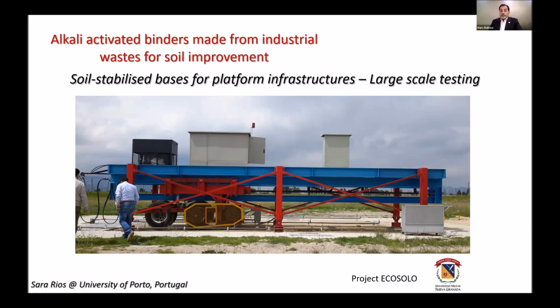Quick question. Do you know if the wheels are going and coming with the same pressure, or are they lifted coming back down? Just curiosity. I think in this equipment, it was really at the beginning when we did this project. I believe now they have more experience with that, but at that moment, the pressure was the same, the load was the same back and forward. I believe they may eventually change that. I would lift it to simulate traffic in one direction. It makes a big difference.